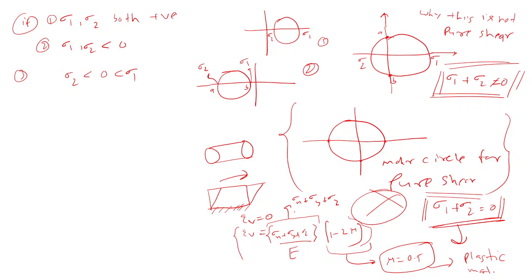But in the pure shear condition, third direction stress is not coming, a 2D stress develops there, so the z terms are not coming, so sigma x plus sigma y, or sigma 1 plus sigma 2, is 0. That is coming by the loading that we have seen. That's why we have said it is pure shear. In the same way, here it is not happening, because sigma 1 plus sigma 2 is not 0. It is asymmetric from here, so some volumetric strain would be there. That's why it is not pure shear.